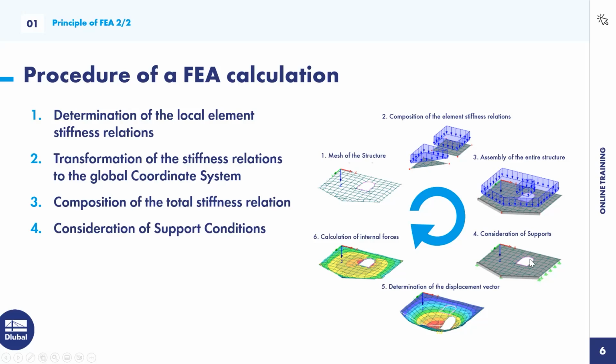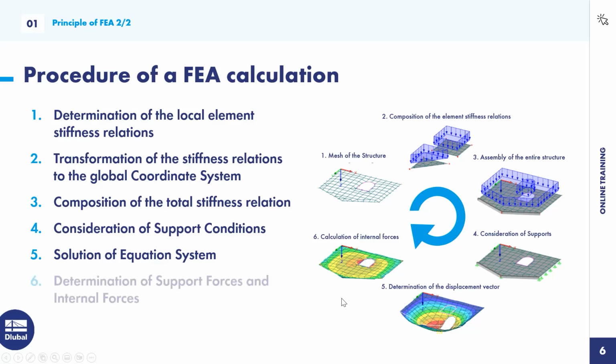We will build this into our equation system, and when everything is set, we can just solve it. That's done right here within our step 5. We will solve the equation system and get our displacement vector. With that displacement vector, we can finally recalculate our internal forces. So that's the whole process.